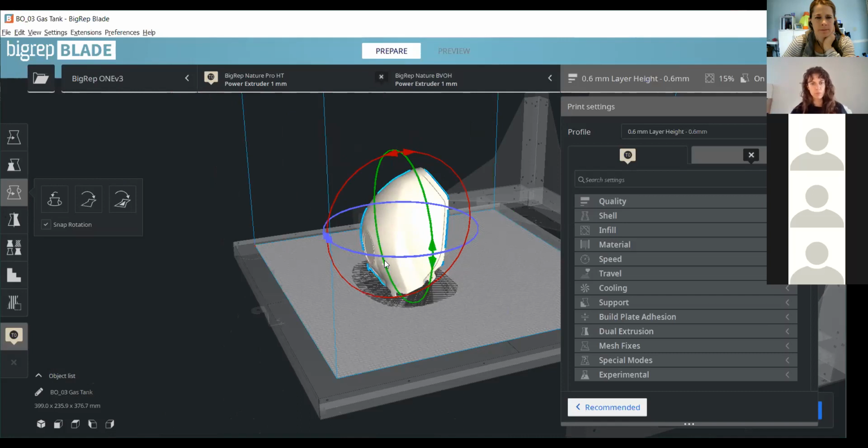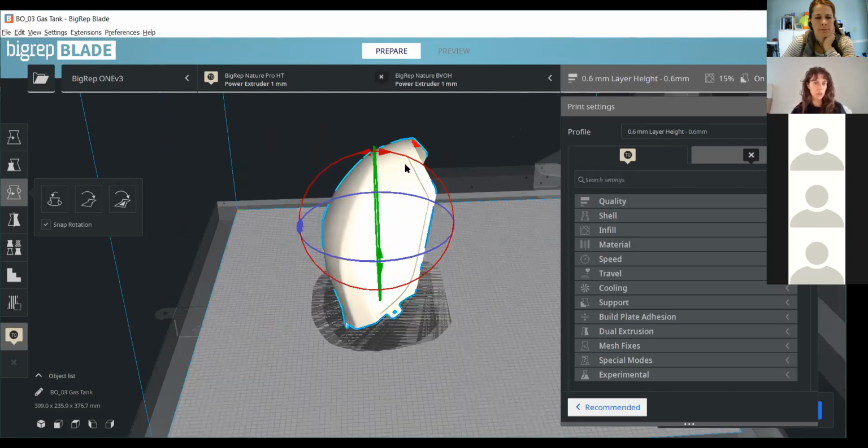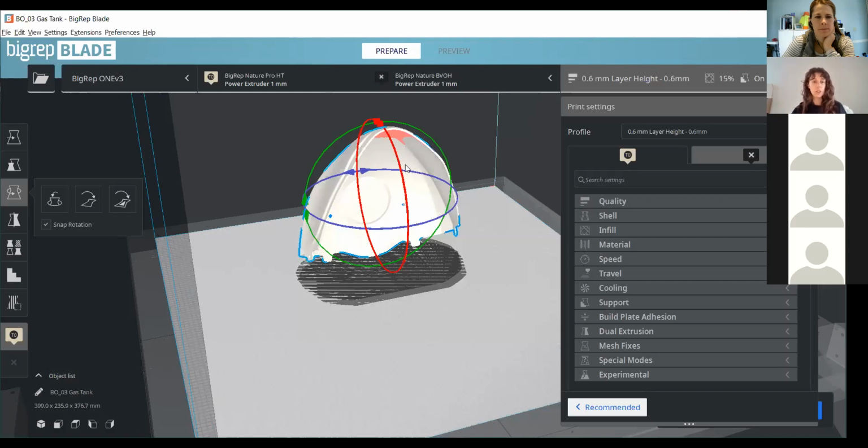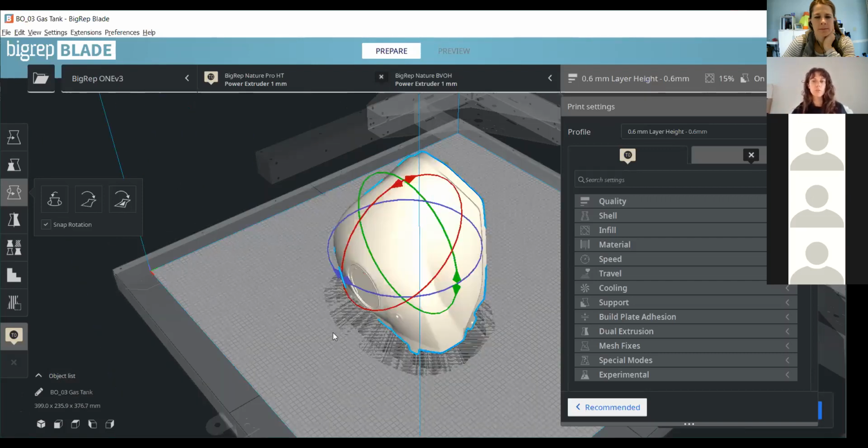This is a prototype for a motorcycle, and it's going to be finished. For example, you're going to want to spray and paint it, and the client's only going to see this outer surface as this is all connecting to something else. So having support on the interior for me, for this example, is totally fine. Keeping this exterior really clean is important.